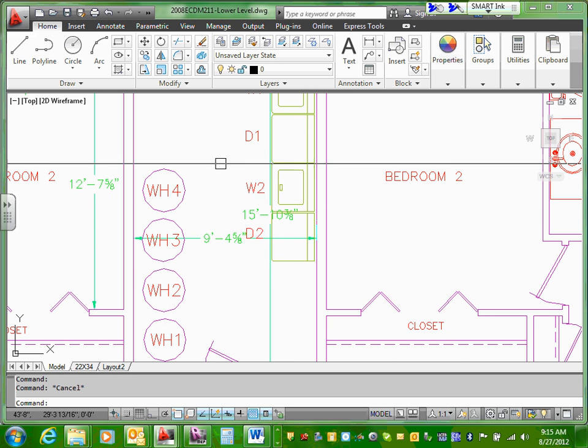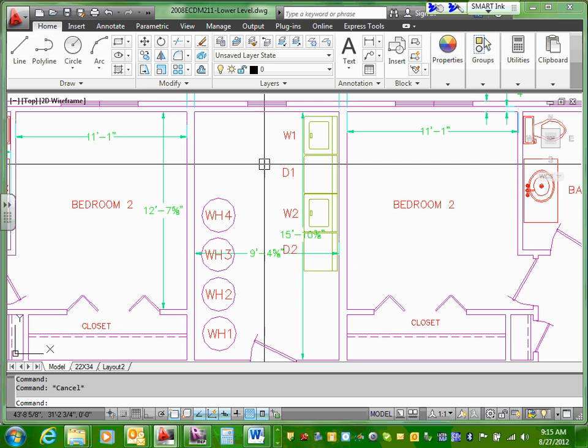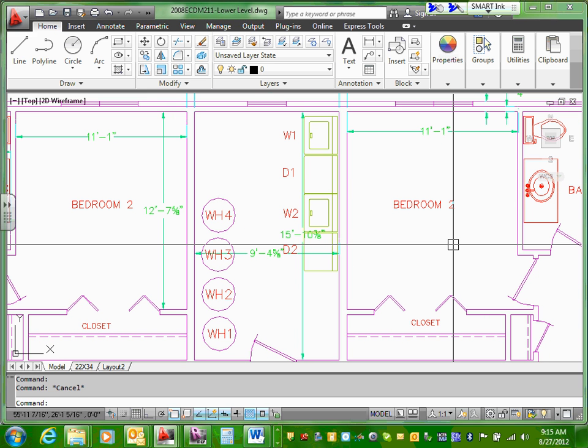Okay. Can everybody give me a thumbs up that we copied them? The reason why we did that is just to give you an idea how to edit the background: copy paste, put them there, rename them, adjust them. And remember, Darren, my friend, and everybody else, and Joe, you can come back at any time and adjust this. So this is not a done deal. It's not like you do it at once. This is Xref. Every time you change it, it will update all your files that refer to it. That's a nice thing about Xref. Can I have a thumbs up that everybody's okay with that?